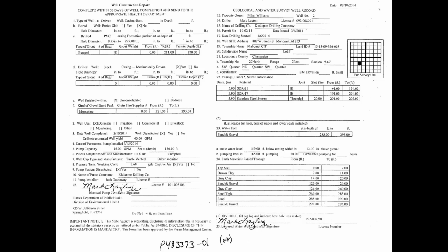So the static water level was 159 feet. So even though the sand didn't start until 260, the water level in the well came up to 159. So that means that aquifer's under pressure. So think of squeezing a juice box. If you squeeze it too hard, the juice comes out the straw. So when you put pressure on a system, it makes the water level go up in the well. And so this is considered an artesian aquifer, or a confined artesian aquifer, because it's under pressure that causes water levels to rise up above it.